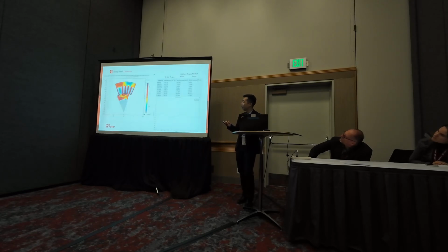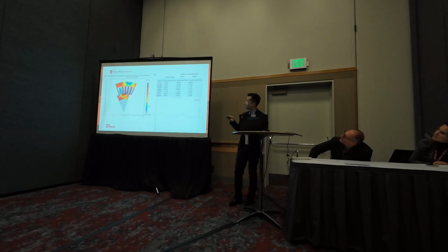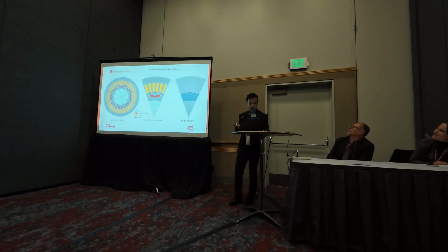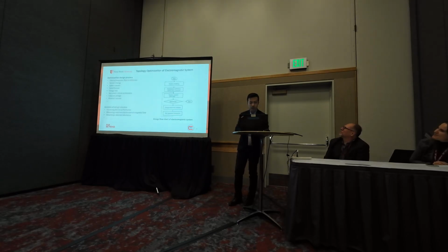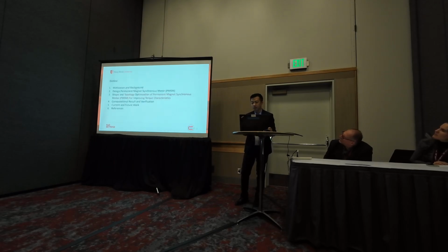And this is a finite element simulation of the reference model, or initial model. We can see the peak value of the remnant flux density is around 2.3 Tesla, and the net torque is around 160 Newton meters.